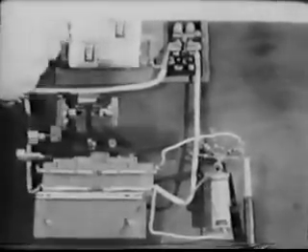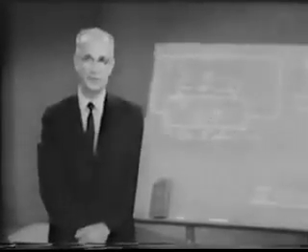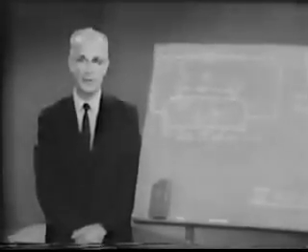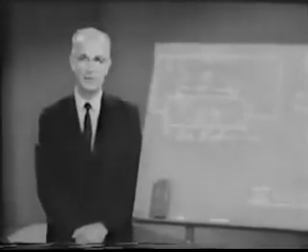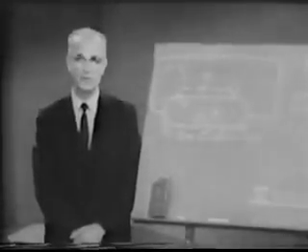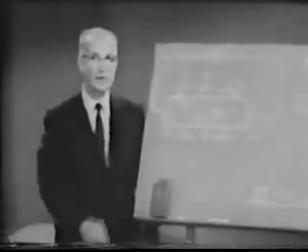The batteries that produce the uniform electric field are here. They are connected through this switch and potentiometer to these large area, low resistance contacts at either ends of the bar. To determine the electric field in the bar, we will later measure the voltage between these two phosphor-bronze wires. These wires are pointed and make small area contacts to the surface of the bar. The detailed nature of the 4 electrical connections to the bar is important. In particular, the right-hand point contact is also used as the detector of minority holes.